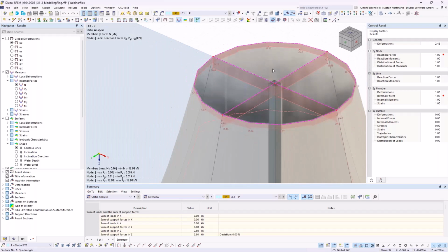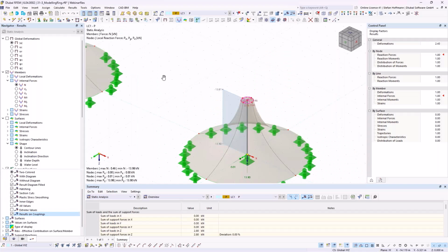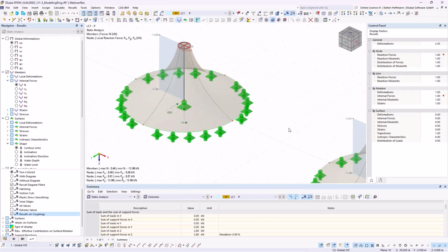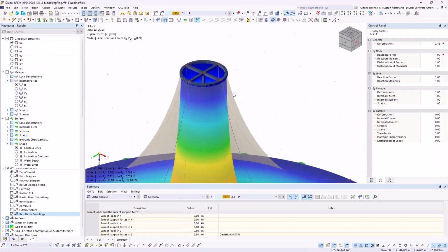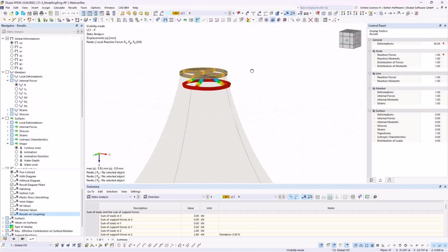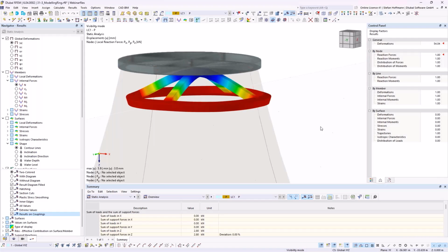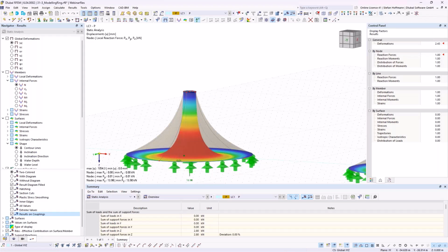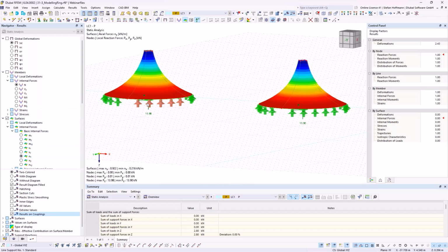So we have here rigid members where you can, of course, also display the results on couplings. Well, the surface will not give us any clue about the forces, but we are able to evaluate surface forces for this. Or we now check the member ring, where it will also most likely be influenced by the stiffness of the member. You can see that it will deform like this, maybe a bit exaggerated. It's only 6 millimeters, but it's not as stiff as the other constructions will be. And it has a small influence on the inner surface distribution.